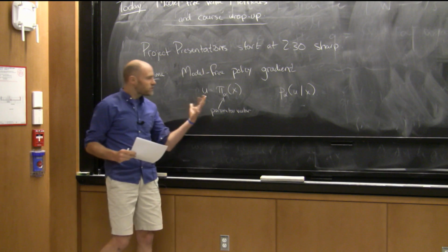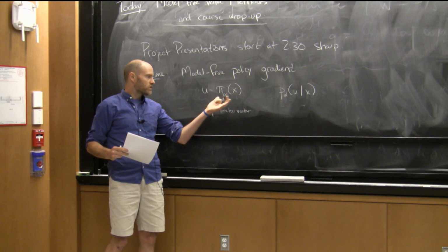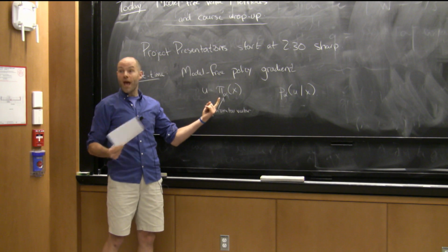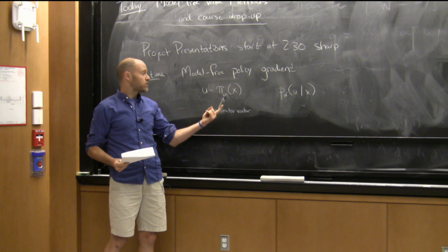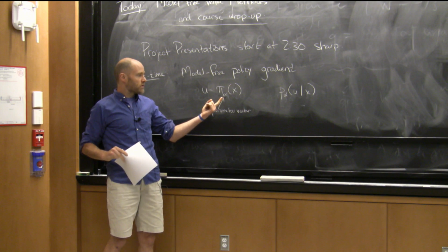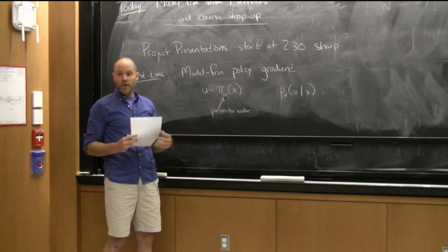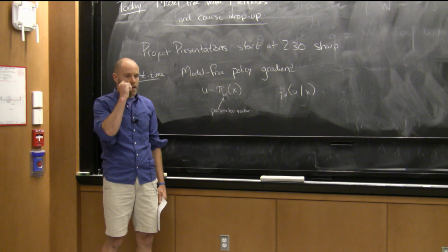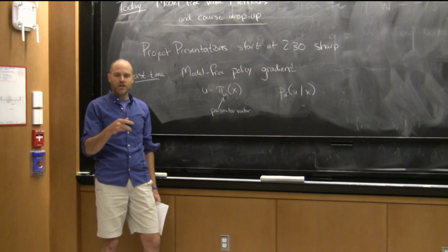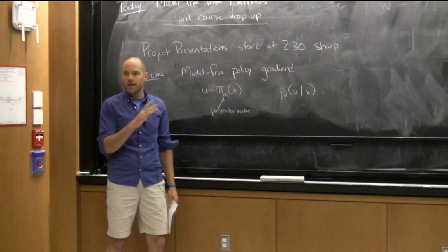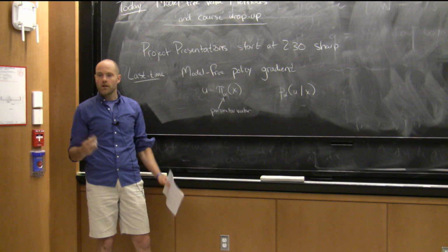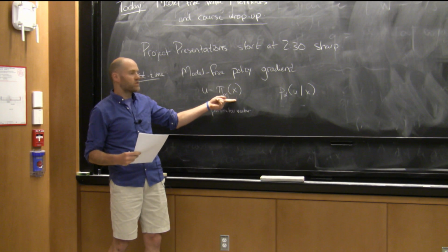There are sort of two ideas connected there. One of them is the idea that you can just search directly in the parameter alpha. You could do that even if you had a model of the system, right? And you could use gradients that you could calculate with the trajectory optimization type gradients, for instance, to optimize alpha. And that, I think, can make sense for systems where, for instance, you think there's a simple representation of the policy, but maybe no simple Lyapunov function or value function or cost-to-go function. Those direct policy search algorithms can make sense.